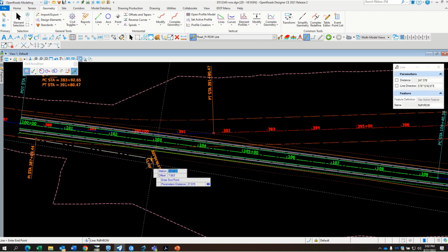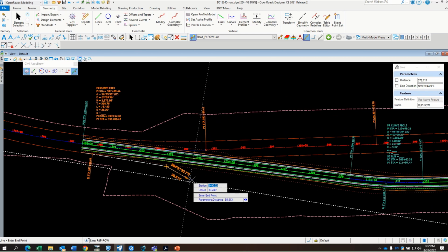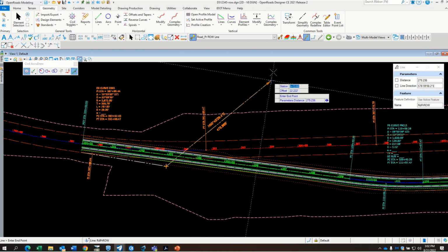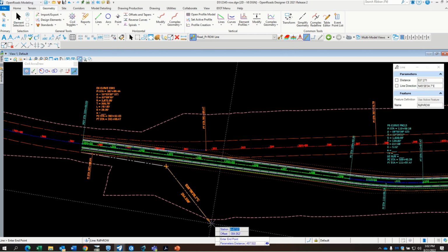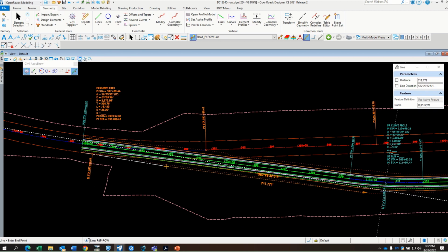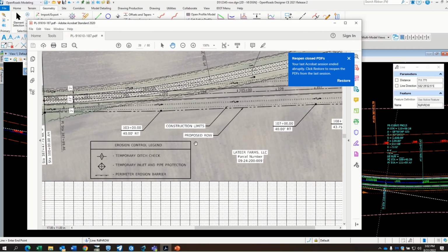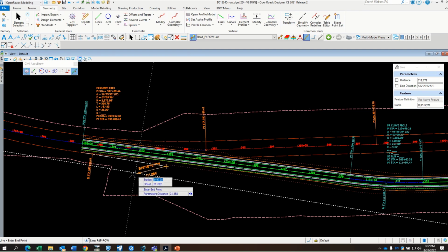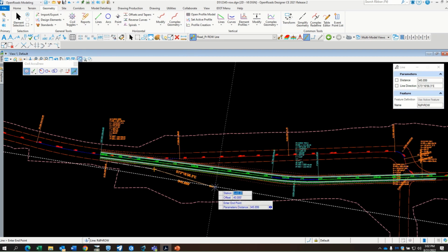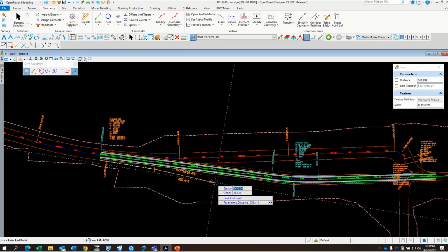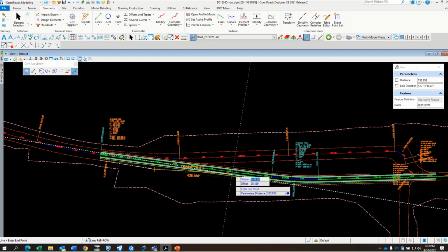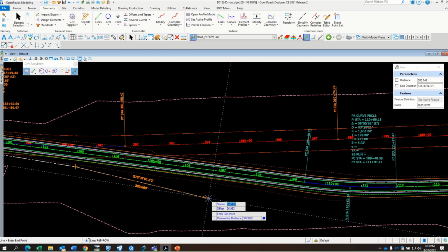and because we have the link up here on the feature definition toggled, it just continues. And so let's just place one more segment. So we'll go with a 107 and offset of 40 foot. We won't do the whole thing. It's just more of the same, just so you get the concept down. So again, hit the origin button to begin with.